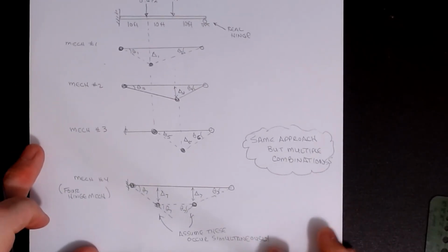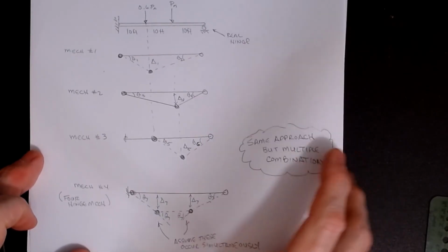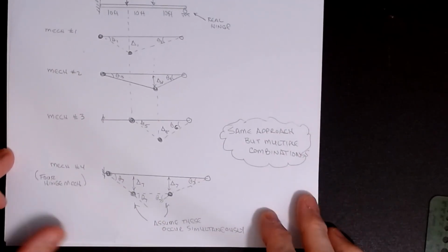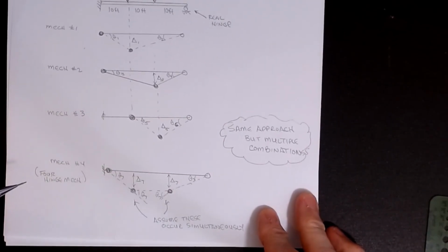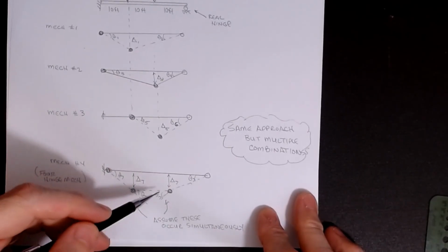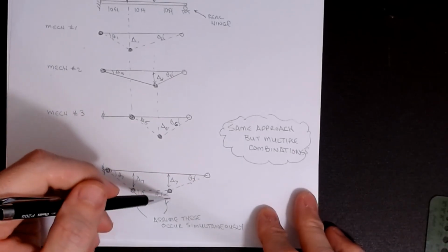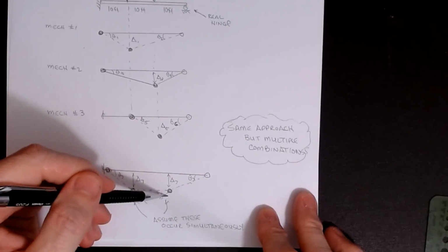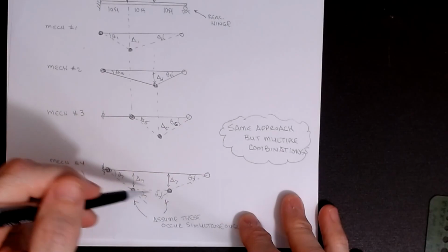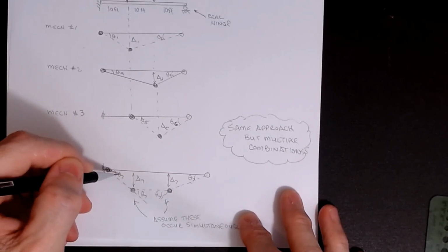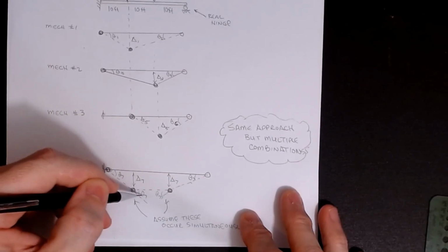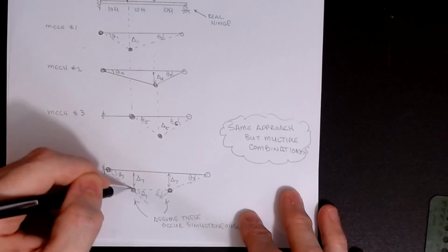Okay, but there is another one that could happen, and this is one that's in your textbook, the McCormick textbook. One of the assumptions that we can make is, what happens if this one and this one form at the same time? Well, if that's the case, then I can get a hinge mechanism such that these two displacements are exactly the same. What we're calling delta 7 on there. And then I would get a distribution that looks something like this. If I call this theta 7, and it was flat originally and flat at the end, then the angle that this guy goes through is also theta 7. Again, I'm just drawing the line and continuing it, right?